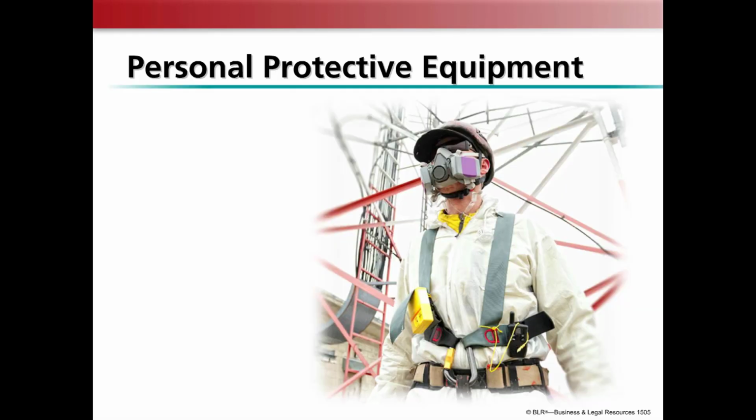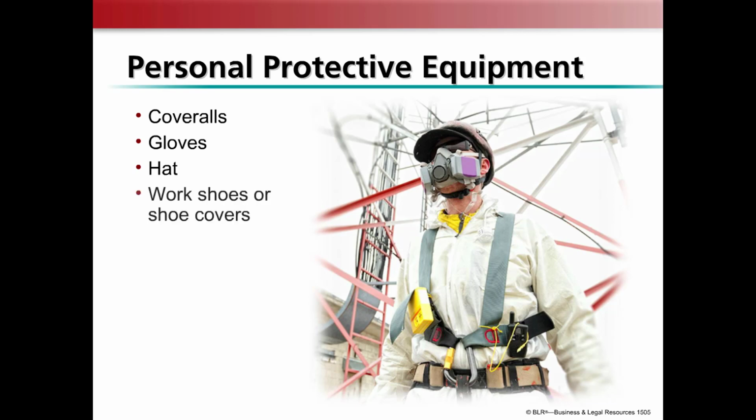We will provide you with appropriate protective clothing and equipment to protect against any lead hazards you may be exposed to on your job. This may include coveralls to protect your body and underclothing from contamination, gloves to protect your hands from contamination, hats or hoods to keep lead out of your hair and ears, work shoes or shoe covers to prevent lead from contaminating your shoes, face shields or goggles to protect your eyes when wearing a half-mask respirator. A respirator if the amount of lead dust in the air exceeds the legal limit.